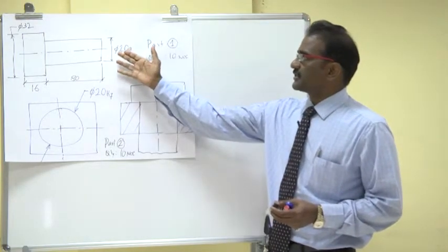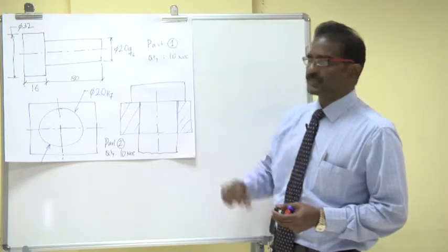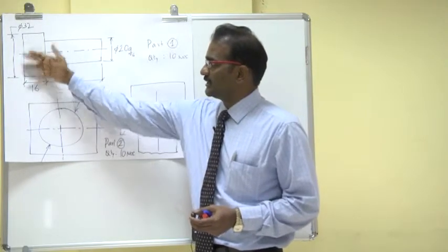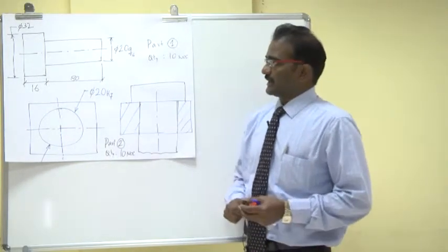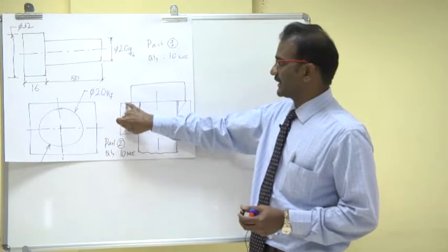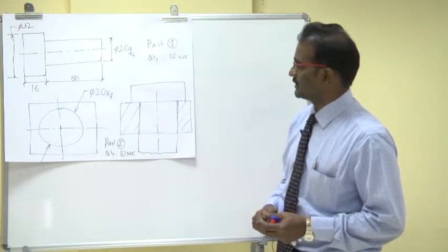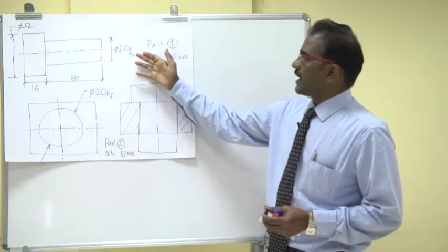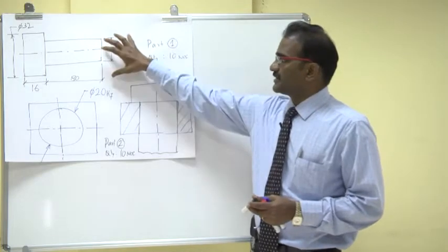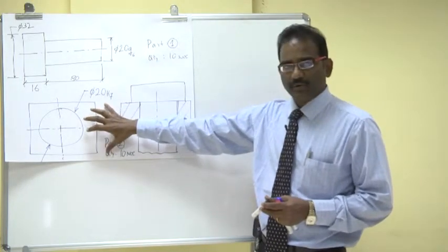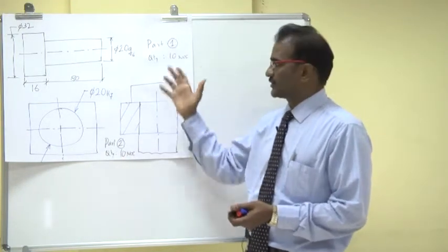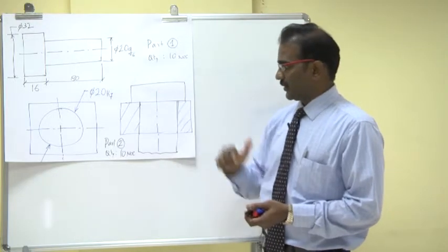Now the shaft dimensions are shown, and the shaft is shown as part number 1 with a length of 80 millimeter, head thickness of 16 and head diameter of 32, whereas the bore is of dia 20, and let us say the plate thickness is 16 millimeter. Each part I am making 10 numbers individually, and I have 10 shafts with me and I have 10 holes with me. Now I am trying to assemble all the 10 pieces together, shaft as well as the hole.